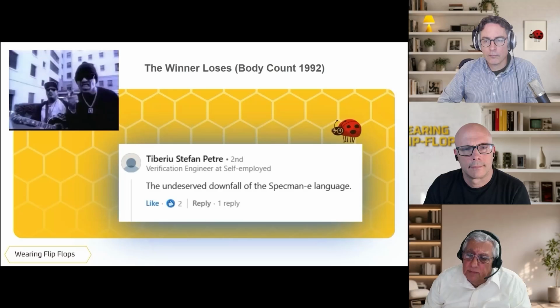The verification environment has three parts, I think. There is stimuli generation, which is very important. This is stimulus activity and trying to explore the bugs. The second one is the checking mechanism. Let's talk just about end-to-end checking, for instance. It should be according to the spec. And the third one is coverage. And these are the three things that are important.